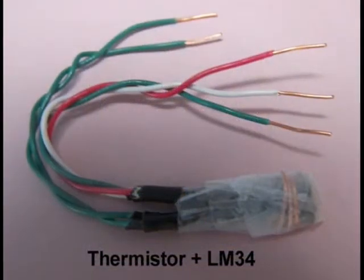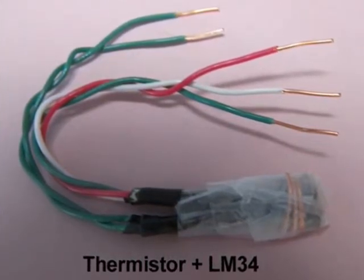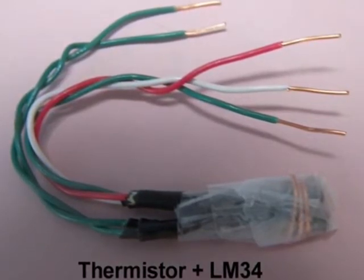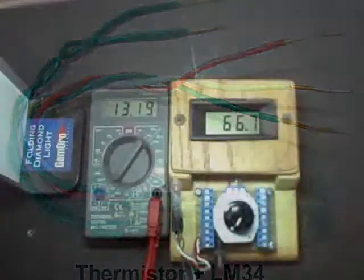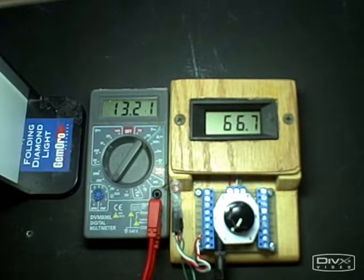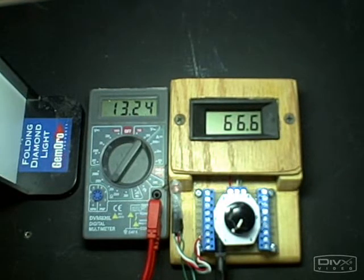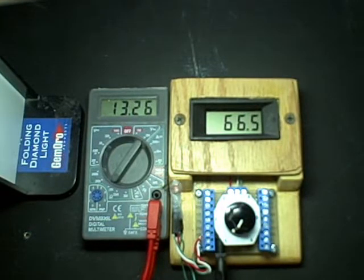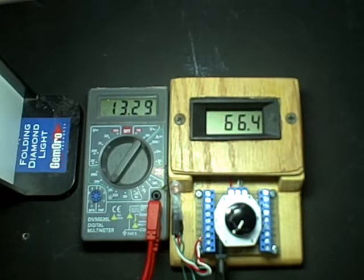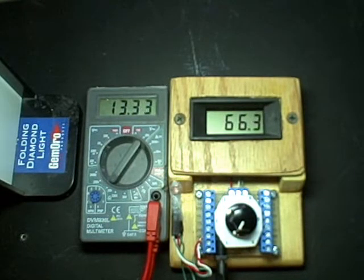If we want to see how the resistance of a thermistor changes with temperature, we can simply bind the thermistor to a calibrated sensor and heat both probes uniformly. The calibrated sensor is bonded to a thermistor, so the temperature of the junction where they both meet should be the same. On the right you can see the actual temperature of both probes. Right now it's 66.5 degrees. On the left you can see the resistance of the thermistor. Okay, so we're starting with 66.4 degrees.